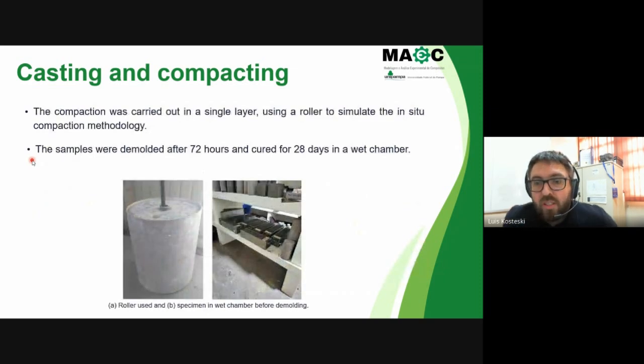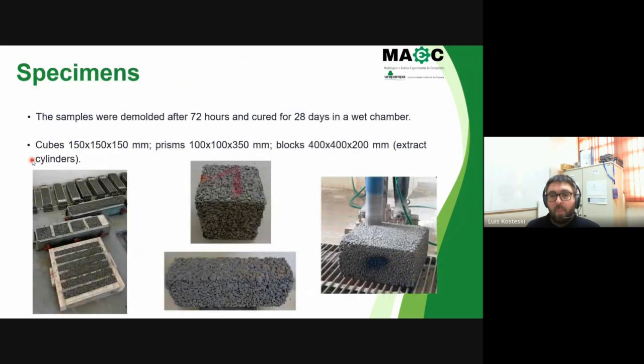The compaction was carried out in a single layer using a roller to simulate the in situ compaction methodology. The samples were demolded after 72 hours and cured 28 days in a wet chamber. After that, we have cubes, blocks, and a prism to make the specimens for the tests.